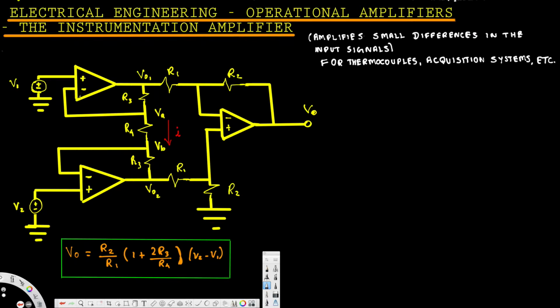Okay, here you can see these two op amplifiers are connected to this one, so the input voltage for the third amplifier is going to be whatever the output voltage is from these two. Now first we are going to calculate the output voltage for these two amplifiers. For these two, you can see the input voltage is connected to the positive terminal, so this is a non-inverting op amplifier. For a non-inverting op amplifier, we use this equation to calculate the output voltage.